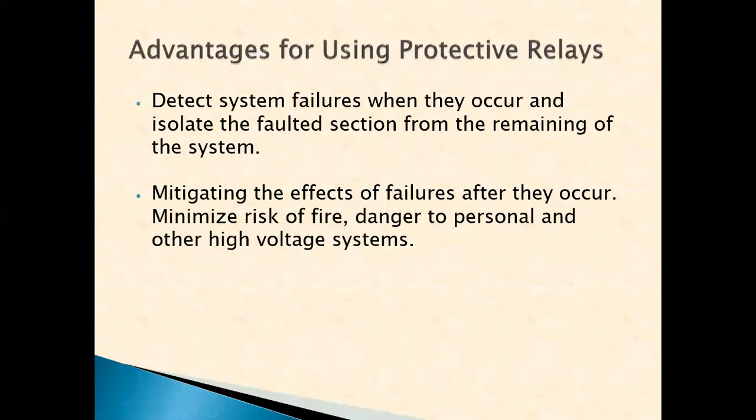The advantages of using protective relays for a power system: it will detect system failures when they occur and isolate the faulted section from the remainder of the system. It will mitigate the effects of failures after they occur, and minimize the risk of fire and danger to personnel and other high voltage systems.